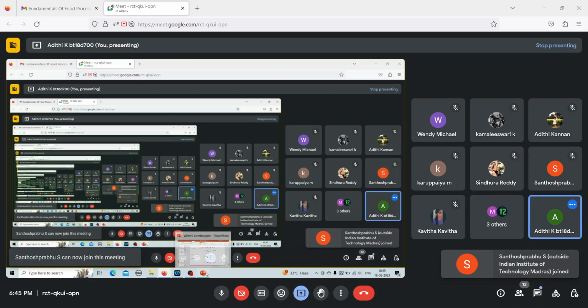Again I am rearranging to find delta T1, which is equal to delta T, and rearranging 1 by U1 plus 1 by U2 plus 1 by U3, with 1 by U1 going on this side. So if you rearrange, this is what you will get.